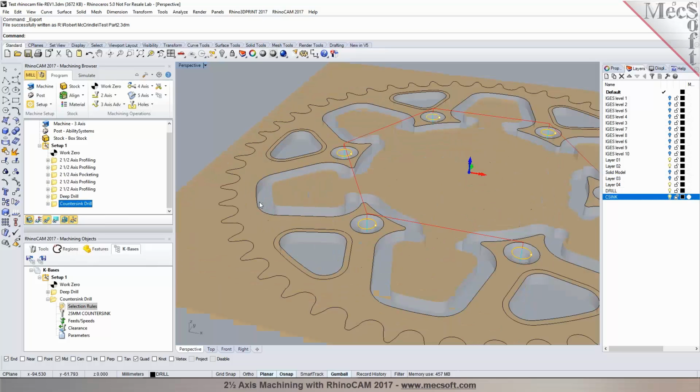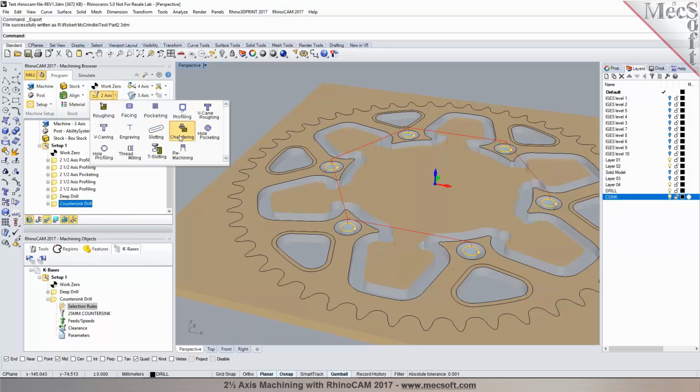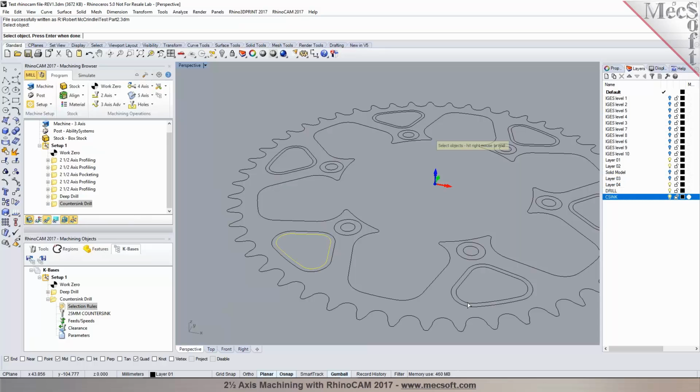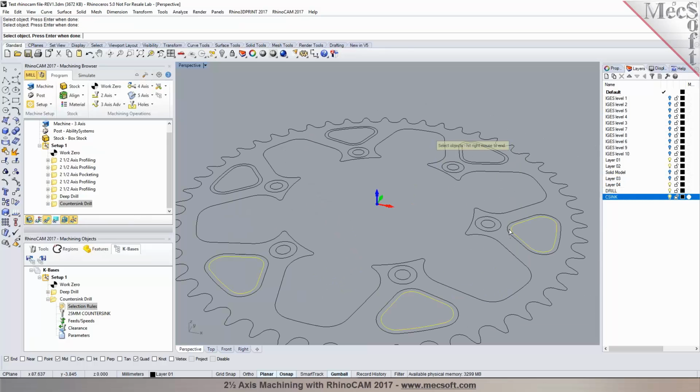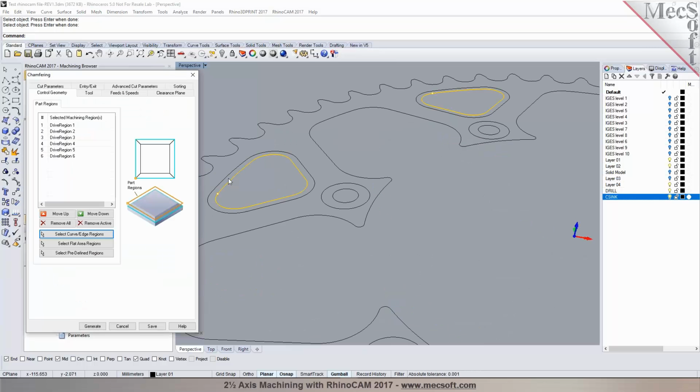The next step is to do the chamfers on these pockets, right? Sure. So you would want to use a 2-axis and use chamfer operation, and you can select these features in here from the viewport directly. And this chamfer is about 2.5 millimeter, is that correct?